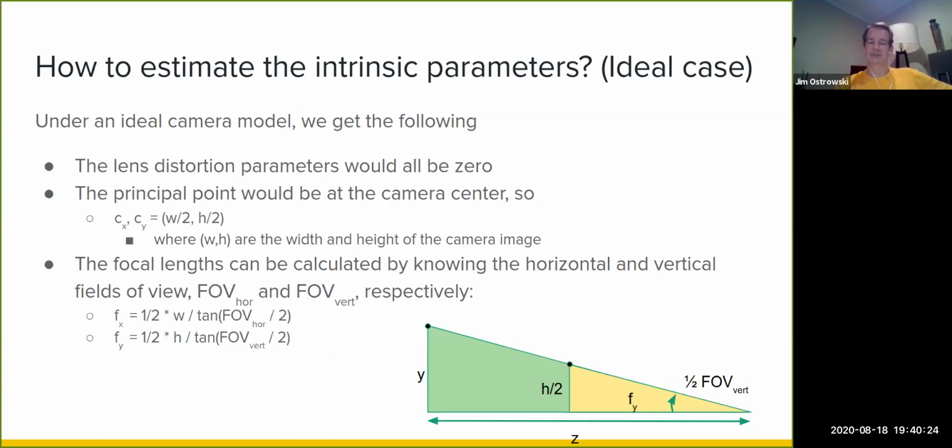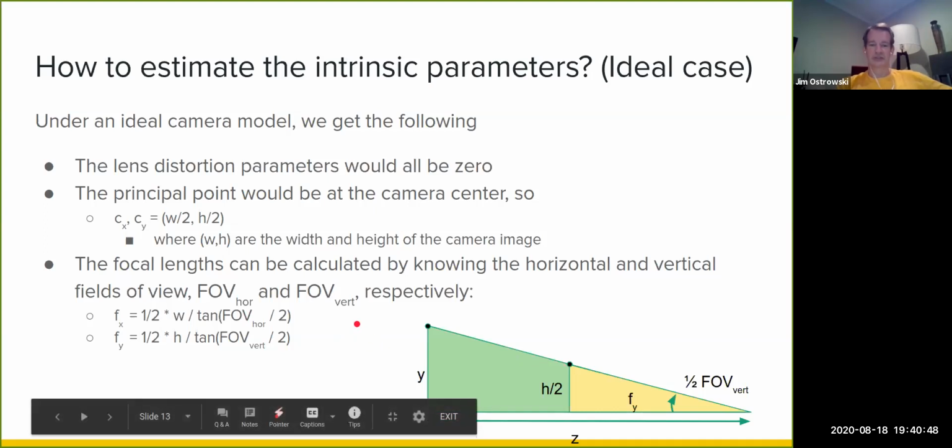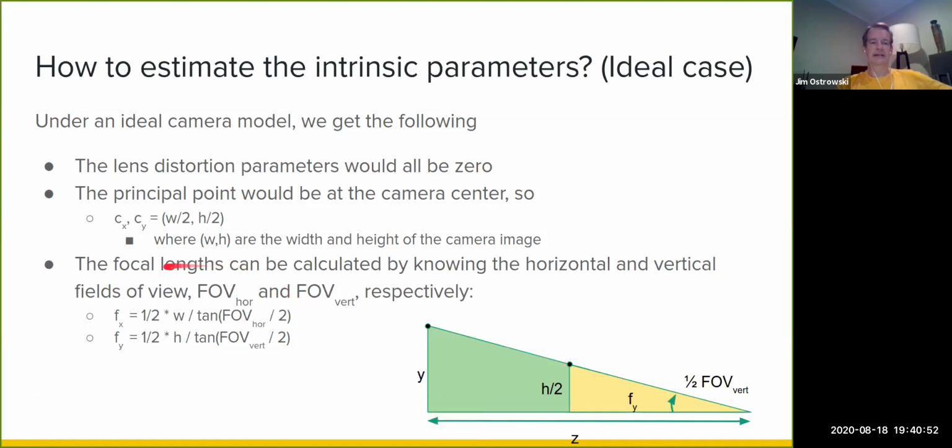As an example, I might have an 8mm lens, and my pixels are like 3 microns wide. So I would divide the 8 millimeters by 3 and get something around 2 2/3 times, I think, 1,000. So it'd be like 2,300 pixels as my measurement for the focal length.